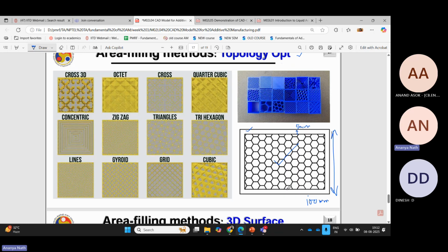But inside that, you put this honeycomb structure, and each honeycomb structure has some wall width, and the white portion is actually empty. This black portion is where you have deposited the material, but it's not this thin. It has some width, maybe the wall width is 500 micron. Then you can save a lot of time, a lot of material, and a lot of cost.